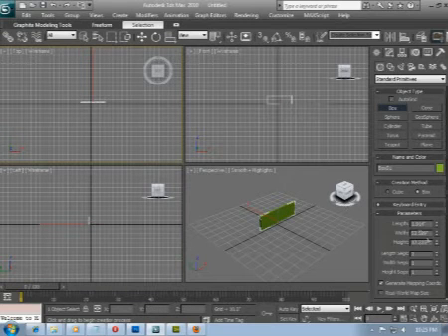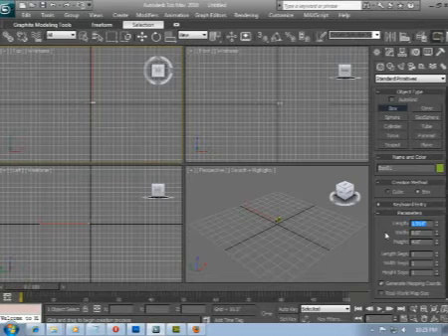And then set the sizes to approximately the size it would appear on a normal display. So I'm thinking I want to cover about 8 inches horizontally, and 2 lines of text means maybe 4 inches of screen vertically. We can trim off the extra in Photoshop, so if we make it a bit big, it's not a big deal. And length is actually thickness here, so 0.1 should be more than thick enough. Notice the segment settings here are all 1s at the moment. We're going to crank the width and height segments right up to 200 later, but the computer just crawls with that many polygons, so we'll hold off on that for a bit.